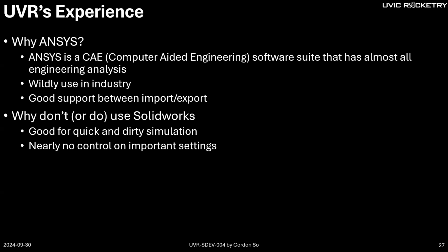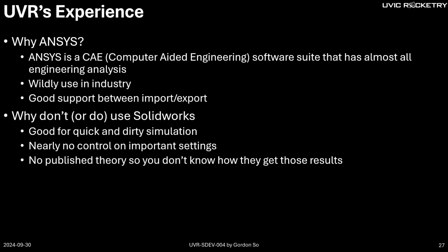However, you have nearly no control over the settings. In fact, the only settings you would use are how you set up your boundary conditions and mesh size. That's basically it. You don't have other controls. They also don't publish what method or theory they use, so you actually don't know how much you should trust the result. So that's really good for quick and dirty stuff, because you don't want to spend too much time on a simple CFD in the beginning. Of course, as time proceeds and with more development, you want more detailed analysis.